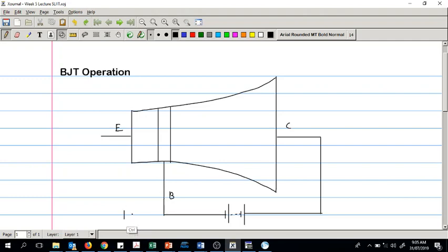Now this is a forward bias, so we know that the voltage can't be larger, because the forward bias voltage of a silicon PN junction is around 0.7, so you don't need a larger forward bias. Okay, so that's the biasing. Now the base-emitter junction is forward biased, so you don't have any depletion layer in here. But what about the base-collector PN junction?